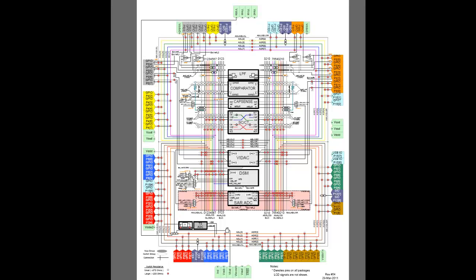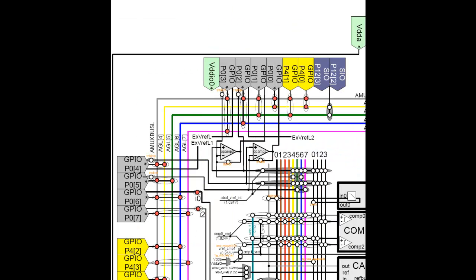Some blocks have dedicated connections between an analog block and a dedicated GPIO pin. One of the most important of these connections are between the op-amps and the associated GPIO pins. The op-amps have dedicated routes between the inputs and outputs to a corresponding GPIO pin. Notice the dedicated switches between the op-amp inputs and the GPIOs. It is recommended that you select these pins when using an op-amp. You will not use up the analog globals that way.